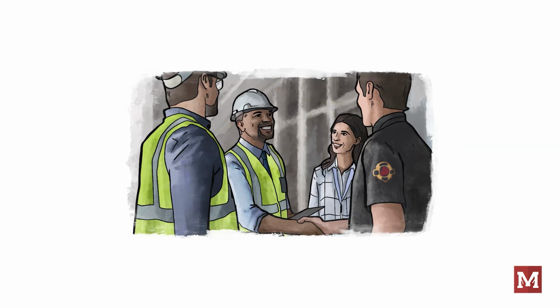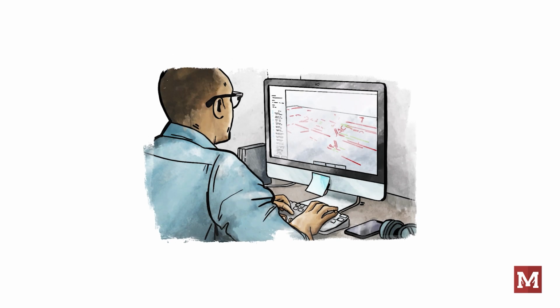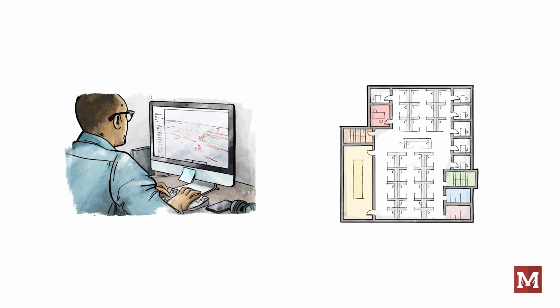The design of a hydraulic fire suppression system involves a number of individuals. Each person has a specific role to be satisfied. The coordination of that work is very important. Often at the outset, a fire protection engineer and system designer rely on the guidance provided by the architect of record. This direction includes the planned occupancy, physical size of the facility, its height, its construction type, any separation barriers that are fire resistive within the building, and so forth.